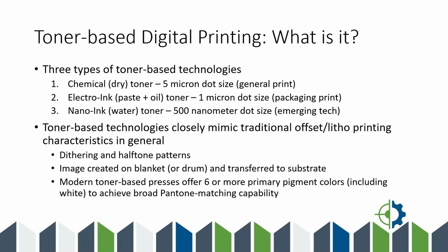With this, you're getting down... this uses water instead of an oil paste. And the particles are so fine, the water evaporates extremely quickly. And you're in the 500 nanometer dot size, which in essence is getting you gravure type technology, 2400 DPI, and an incredible amount of future gamut when you get into different colors of the nano ink. But that's just emerging, and we'll see a lot more of this over the coming years.